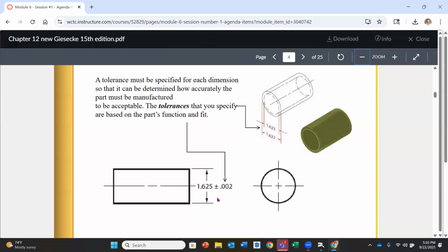But if my target is small that I'm hitting, my tolerance is small that I'm trying to achieve, now all of a sudden it takes longer time to get there. It might take multiple passes, for instance, on a milling machine. Or I might have to take it off of a current process, put it on another in order to achieve maybe some other tighter tolerances or very smooth surfaces or something like that. Well, each time I have to move that part, each time I have to take more time to get to the smaller target, it costs more money, right? Time is money out in industry.